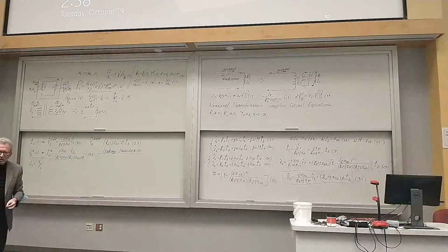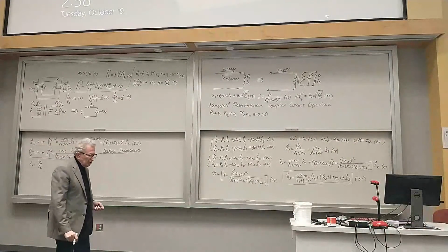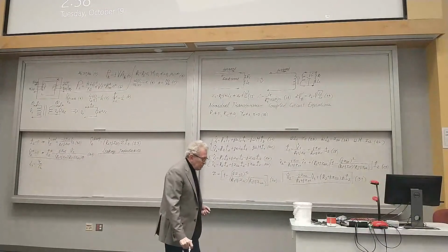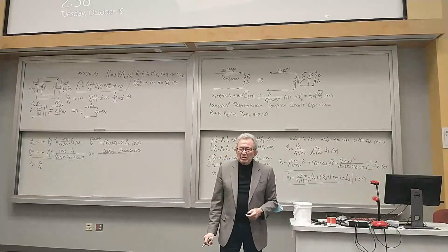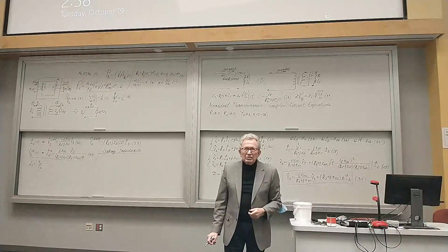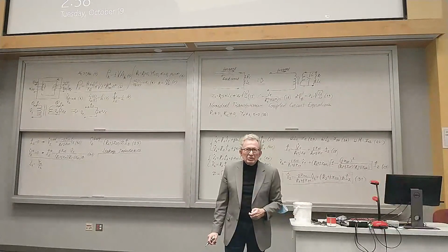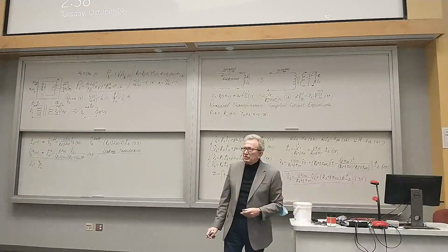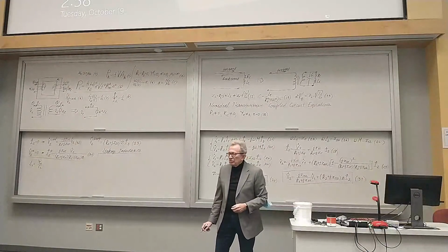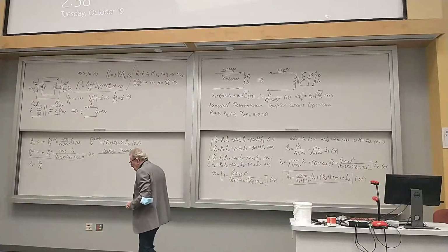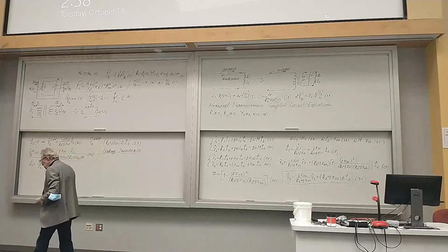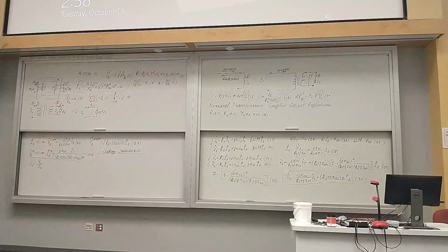And if you read it in my book, you should know this from 380, that inductance does not depend, strictly speaking, on the flux linkages and current. It depends on the number of turns, usually proportional to the square of the number of turns, if you neglect displacement current between the turns, which is not always the case when you deal with high frequency applications, especially integrated circuits.